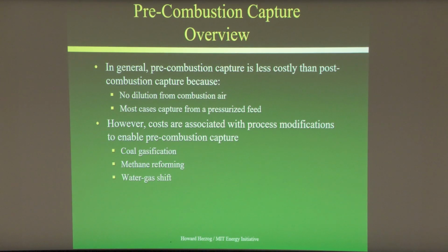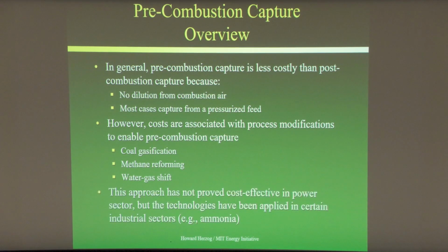Instead of using a boiler, you're using a coal gasifier, or if you're using methane, you're going to have to reform the methane. In both cases, you're going to need a water gas shift. So, as I say, the CO2 capture itself is cheaper, but